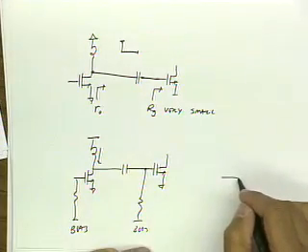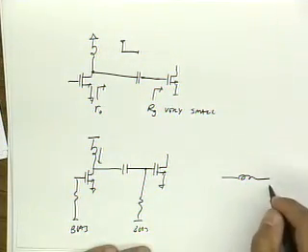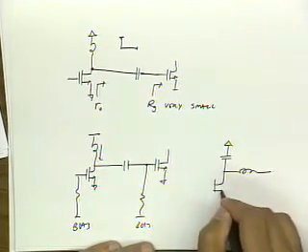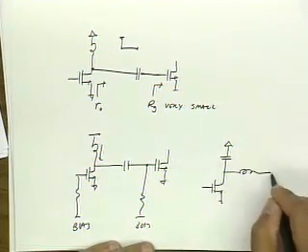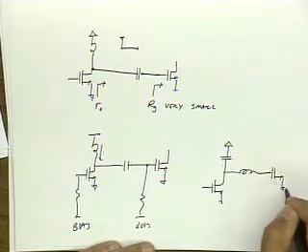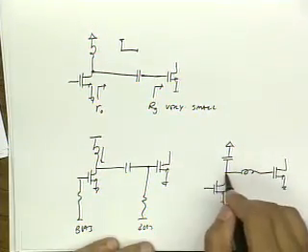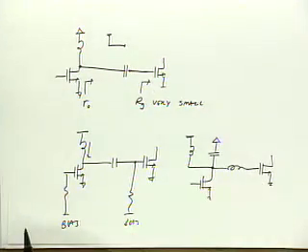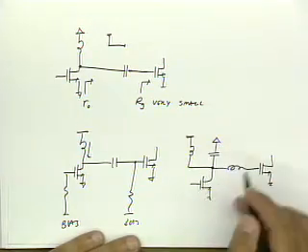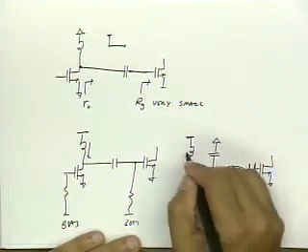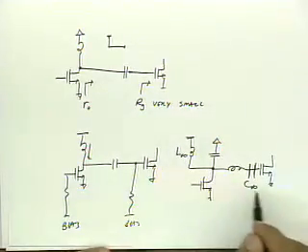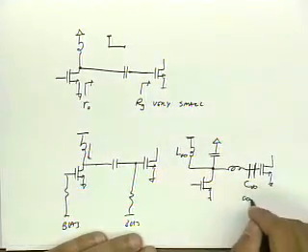So, for instance, if I wanted to do a low-pass, do something like this, but I still need to provide DC current, so I actually need another inductor here. And now, basically, I need to provide another capacitor. So this is L infinity and this is C infinity. We call this a choke and we call this a coupling capacitor.